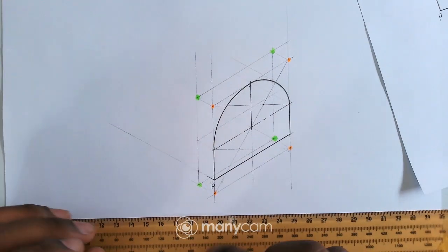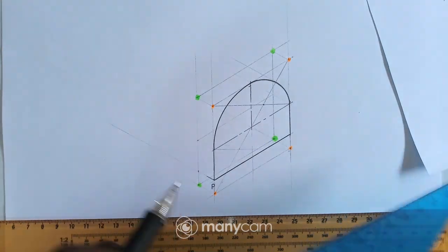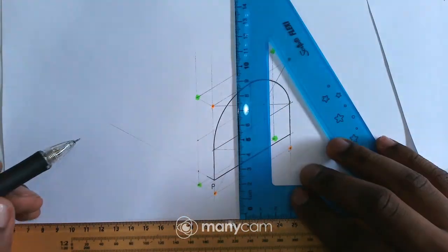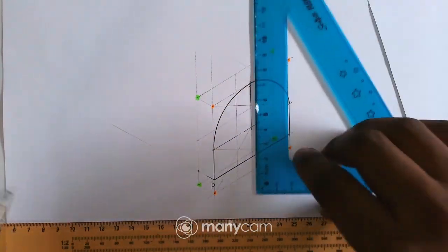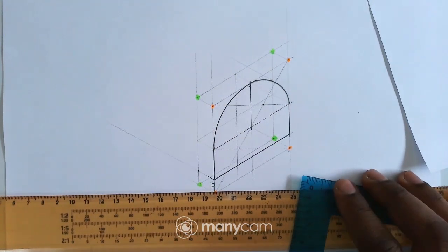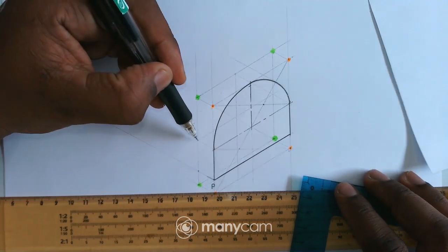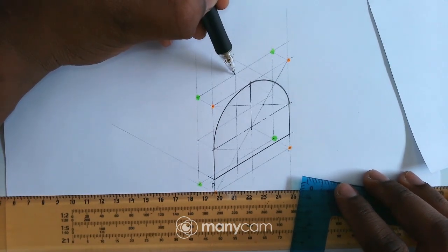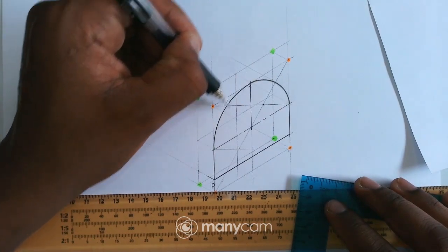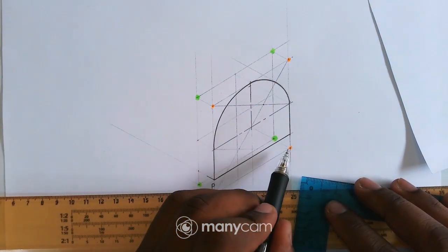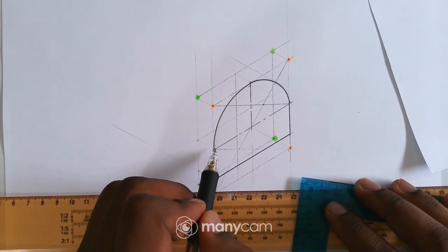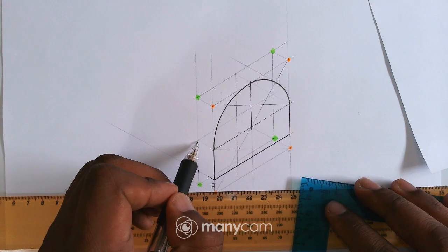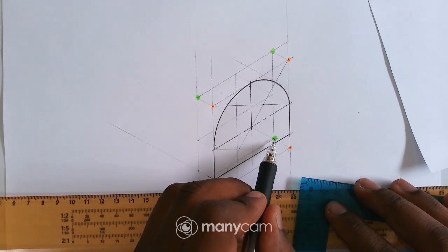Okay, so now I can just proceed. I forgot to project the center line there, the vertical one. Okay, just like that. Okay, now I can just start by drawing my arc from this point to that point. And remember, for this arc of this section there, I put my compass at this point, and then I drew that arc. So now, because I want to draw the same arc at the back there, I have to move the point now 12 millimeters up. So it means now I'll put my compass right there and then draw the arc.